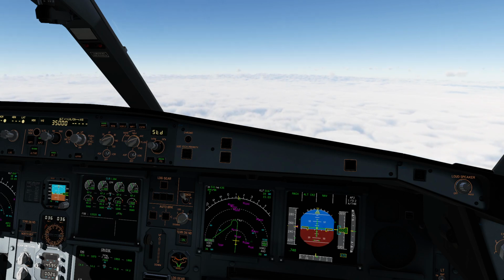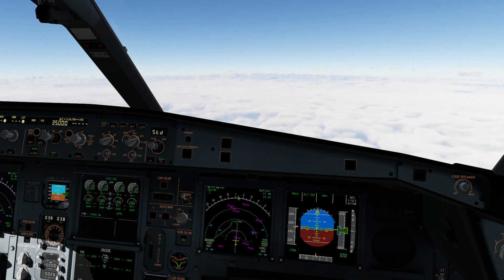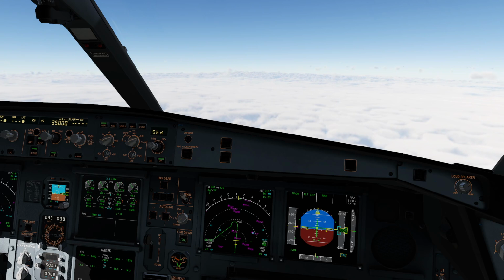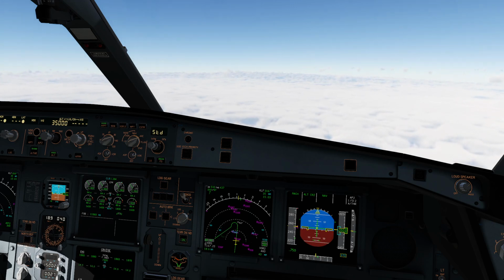Let's talk a little bit about some basics of Airbus logic. The cabin pressure excess cabin altitude alert on the ECAM, even if not confirmed on the cabin pressure SD page, must be relied upon. The alert can be triggered on the ECAM by a cabin pressure sensor different from the one used to control the pressure and display the cabin altitude on the system display. If the excess cabin altitude alert is not triggered, the flight crew should only initiate the emergency descent on positive confirmation that cabin altitude and rate of climb are excessive and not controllable.